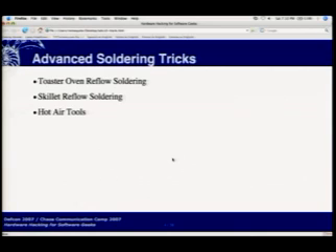Reflow soldering is a process that uses powdered solder and flux to basically bind the chips to the board temporarily, and then the whole board is baked. The flux burns off, cleaning the parts, and then the solder melts and fixes the part to the board. Usually a commercial IR reflow oven is a $2,000 to many tens of thousands of dollars device, depending on controllability and also how many boards you can put through it.